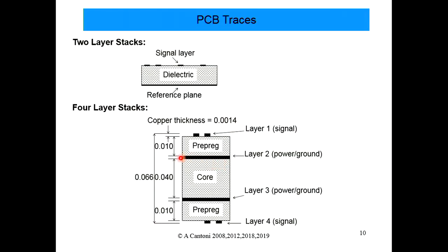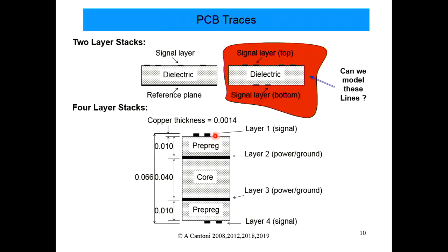And then they would have different layers to actually transport the power or the ground, and you have the different signal layers separated on either side like this, okay? So the actual transmission line is formed with the signal line and the ground line, okay? So that's the two ports, one here and one there, and the actual signal propagates along those, okay?